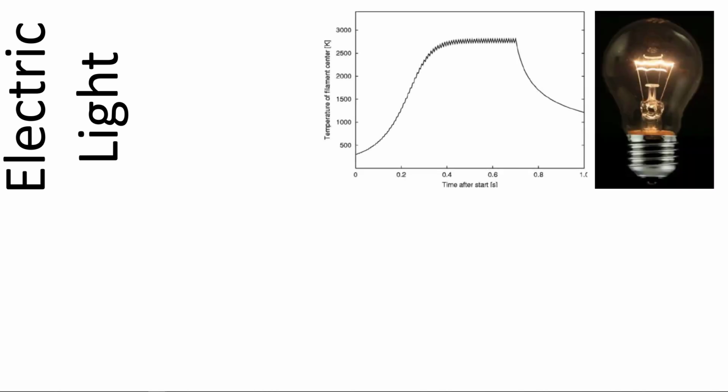So electric light. Well, obviously there's the incandescent light. We're all familiar with that. And notice that this incandescent light, look at the temperature of the filament in Kelvin. That's 2,700 degrees Kelvin. That is warm white. So if you go to the store to buy yourself a light bulb or a fluorescent light or LED light, they are rated in temperature in Kelvin. 2700 is about the lowest, and that's a warm white. Typically, incandescents are warm white because it is thermal.